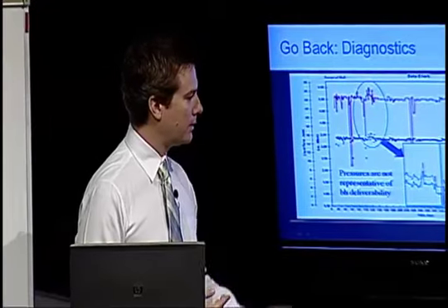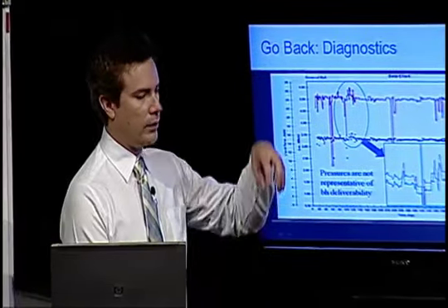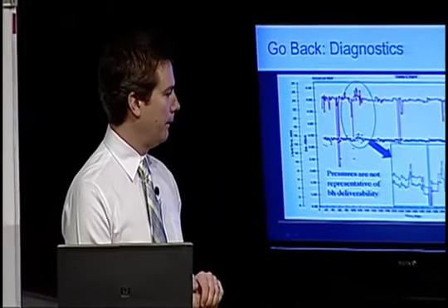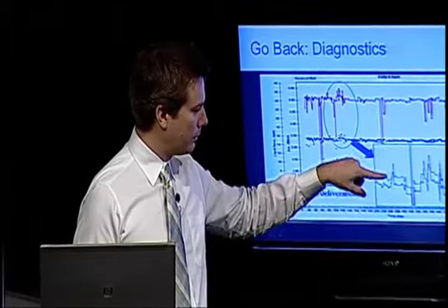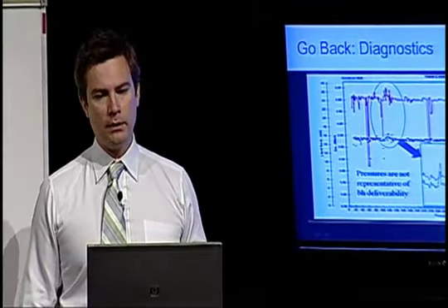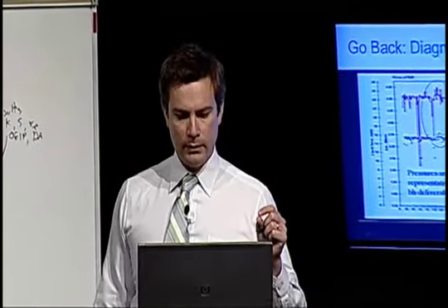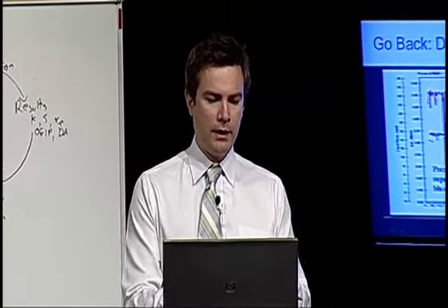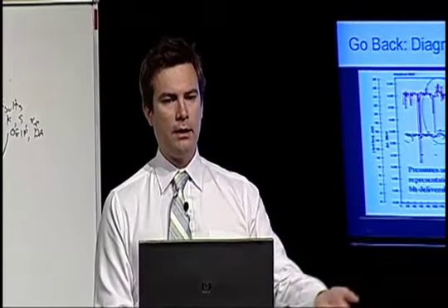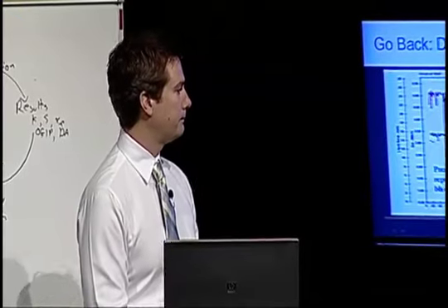Production rates and pressures should have an inverse relationship with each other. In other words, if the production rate jumps up, the pressure should go down to correspond, because we know that the way reservoirs respond is opposite to the pressure. If I increase the back pressure, I get less production rate. If I decrease the back pressure, I get more production rate coming from the reservoir, coming from the sand face.